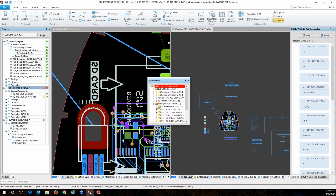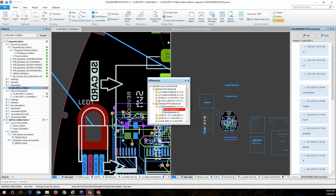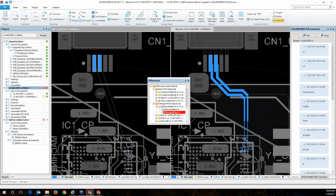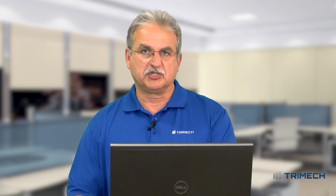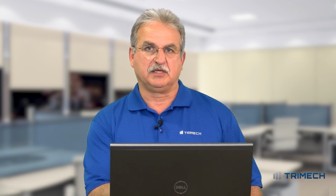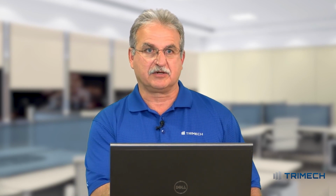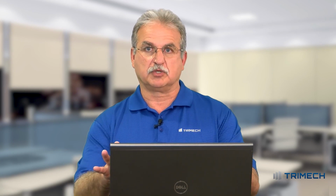This differences box is going to open up, and I'm going to be able to go ahead and click on that. It's going to highlight that diff pair I was just doing, and then it's going to also highlight the one I did previously. Now you notice the shapes are different here versus here. A nice visual of differences, not some ASCII file that you have to go in there and parse through. Imagine using version control when you're doing the MCAD, ECAD interface with this tool. You'll have points in time when you send something to mechanical and when you got something back, and do a visual compare that way.